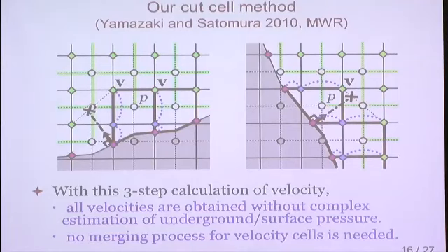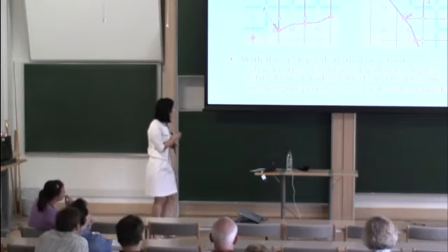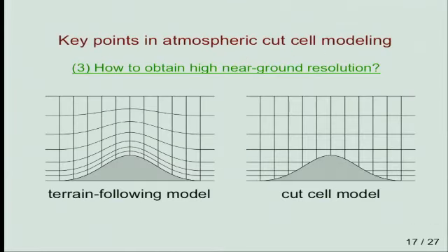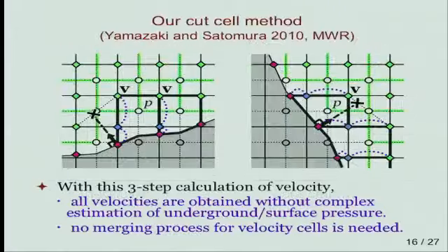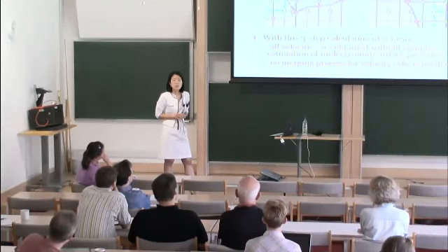Yes. So we basically avoid pressure gradient calculation near the boundary. It sounds like because you're interpolating for the blue points, you've actually reduced the degrees of freedom in some sense. Yes. So when you had a merged cell where you got rid of the degree of freedom and the buoyancy, you also did something similar. Yes. So there isn't an extra degree of freedom.